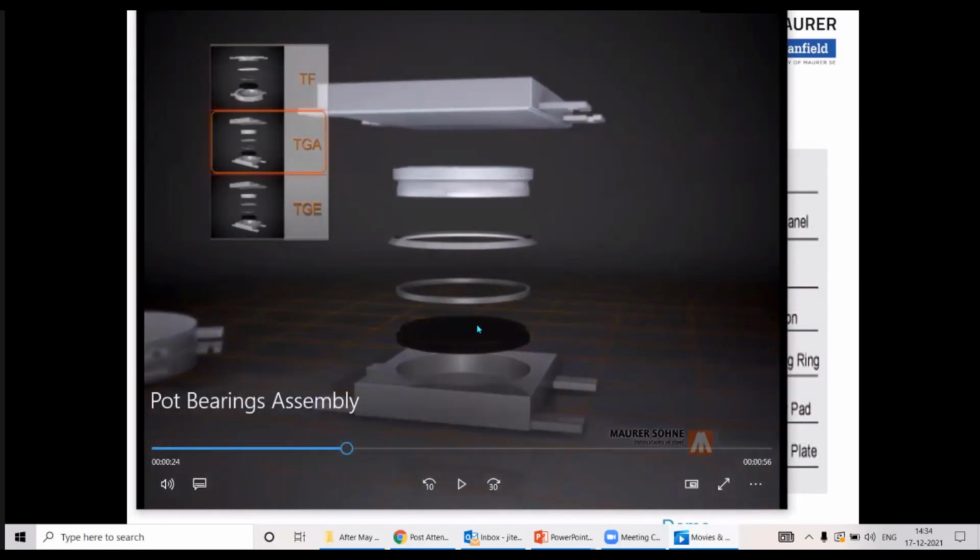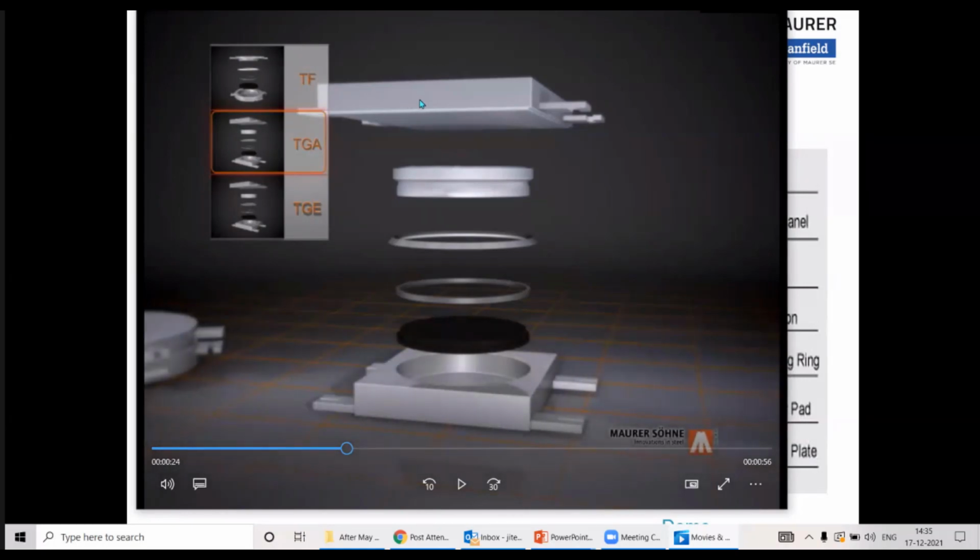And when the bearing is required to take movement, the piston design or shape is changed and it is provided with a sliding material on top, normally PTFE. And a third additional component is introduced, which is a flat sliding plate on top. And this slide plate is provided with a thin sheet of stainless steel underneath.